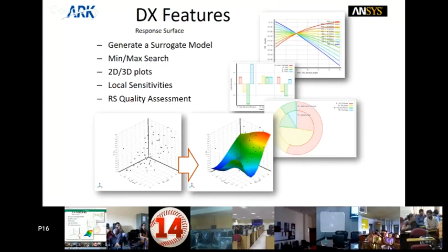As you can see here, the graph at the extreme left is your sensitivity correlation graph, which you have obtained by carrying out various sets of design of experiments. Here each and every point is the result of each experiment carried out on each and every parameter, which we call design of experiments. Now based on the scattered graph obtained from design of experiments, the solver will explicitly trace the entire behavior of all the points taken into consideration, and based on that it will create a response surface.